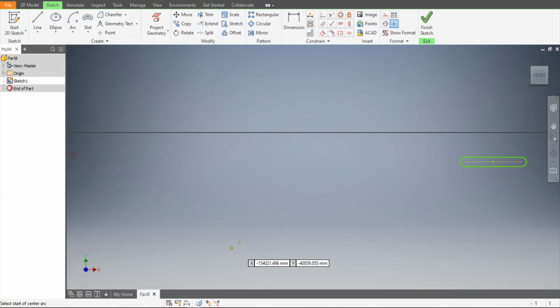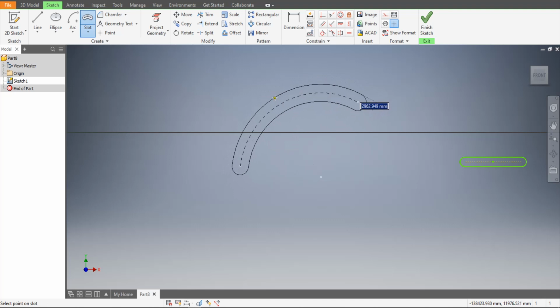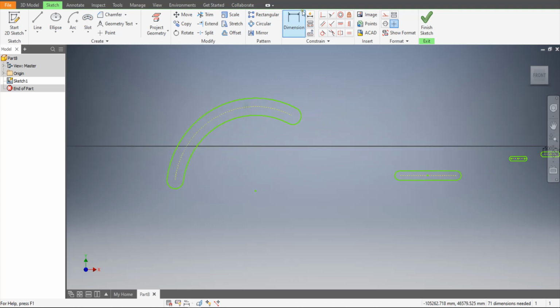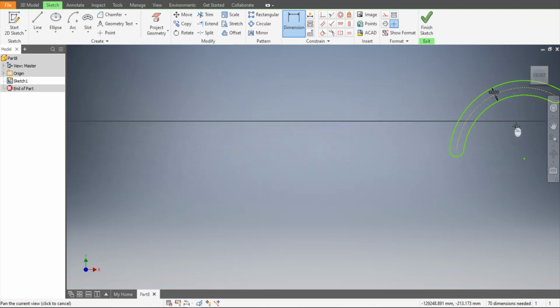Slot 3 points, first point, second point, and this is the third point, like the rectangle, but it is a slot. Once you select the third point, you want to select the thickness. Anytime you can change the dimension, say that dimension between this circle and this circle to be, as example, 6000, and you can change this radius or diameter or angle or this radius or that radius, and the center location. You can add more constraints.